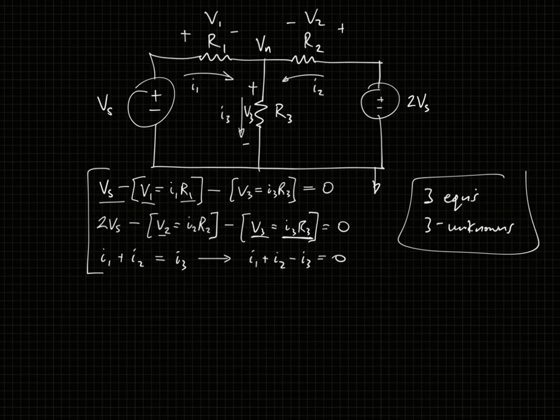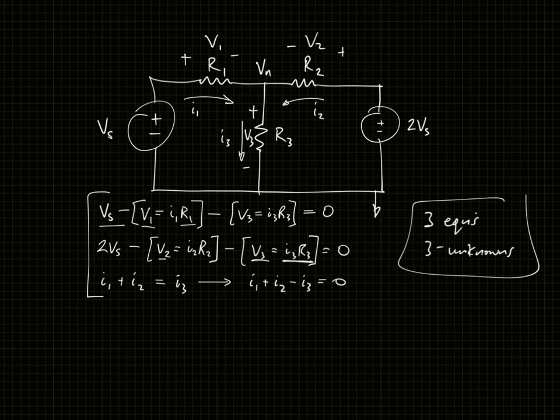So if you take a look at I1 here, in relation to this, the voltage here at this node, by the way, voltages are always the energy at one location with respect to another. And a node voltage is always the voltage at some location with respect to ground. That's the definition of a node voltage. So you know automatically, since this was labeled Vn, it's the voltage here with respect to here. It's not the voltage here with respect to here. That's V2. That's actually minus V2, if you want to be technical about it.